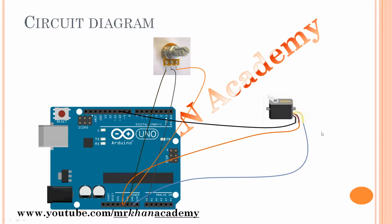and the last one we need to connect with the ground. Sometimes, in some applications, the wires are changed. It might be that the last wire needs to connect with the digital pin and the first wire with the ground. You need to check the data sheet which is available with the servo motor and make the connection accordingly. If it is not working, please swap the first and last wire. This is all about the circuit diagram.